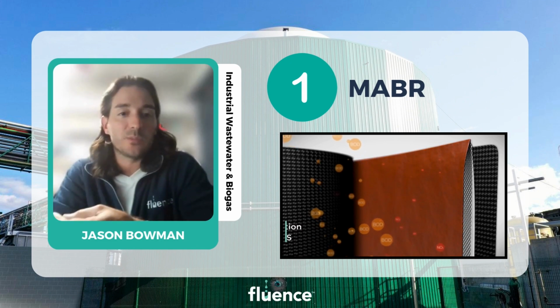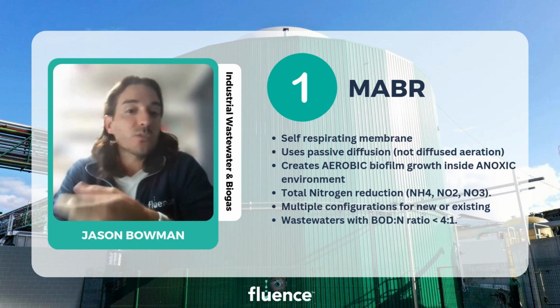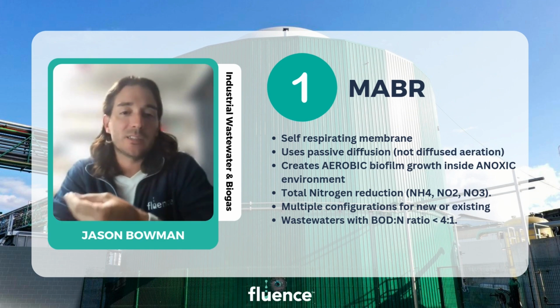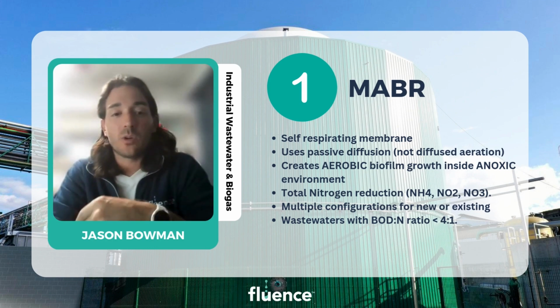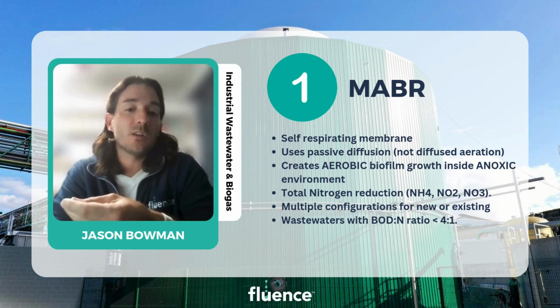So the beauty of these systems is that it's highly effective at total nitrogen reduction compared to, say, conventional treatment or an MBR process. The energy consumption is typically less than half of other systems, so highly effective in that regard. The main disadvantage to this tech is that there is an upper limit to the COD and nitrogen ratio. This is because the heterotrophic bacteria, that is the bacteria responsible for nitrate reduction and COD reduction, grow much more quickly than autotrophic bacteria. So we aim to prevent the buildup of unwanted bacteria on the membrane directly.